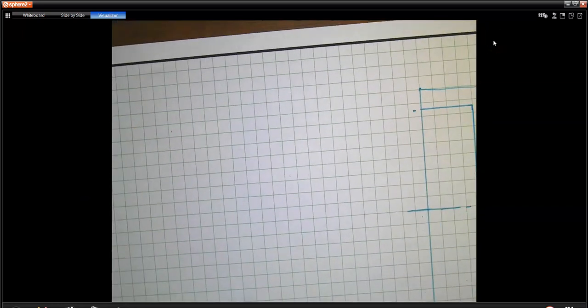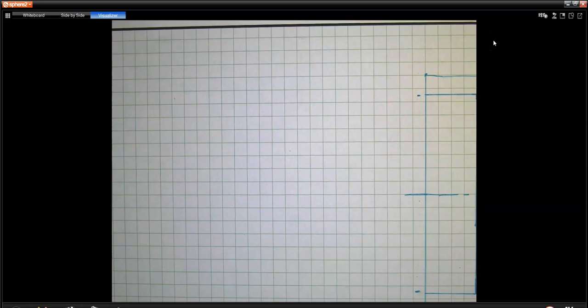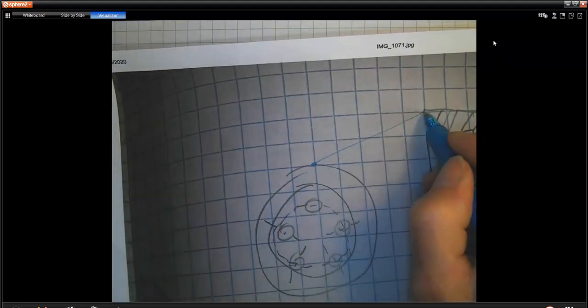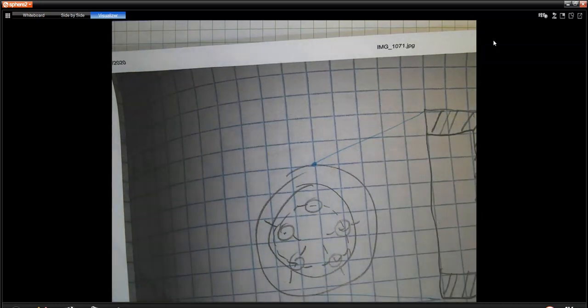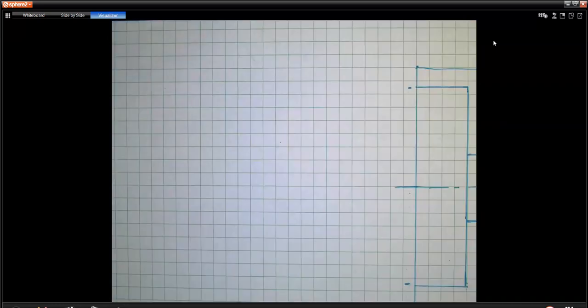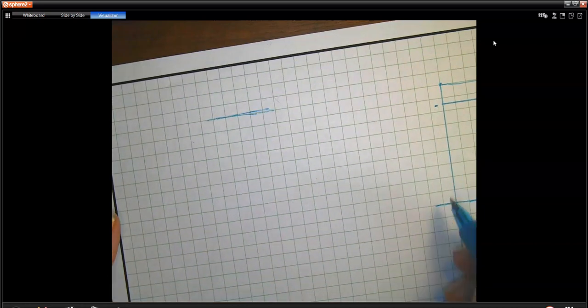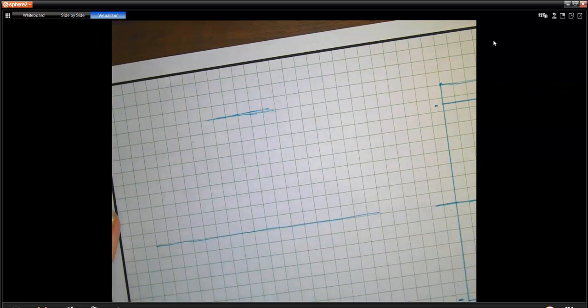So when you lay this out on your front view, this is where it's important to project your lines and get that lined up. So I know you're sketching by hand, but even though you're sketching by hand, I would expect this top right here to be in line with this right here. You kind of made that really small, didn't line up, so you want to make sure that you're projecting that over and you have a general idea of where that center is going to be located. All right. So the center line is still going to be the same. I'm going to just kind of sketch that in for the center line.